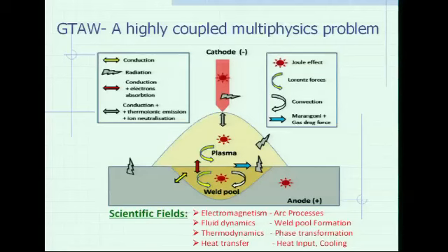And in this weld pool, you have many forces. The first one is the Joule effect, so heating. You have some Lorentz force due to the electromagnetism problem and the field induced by the electric current inside. You have also some convection, called buoyancy force. That means when you heat a fluid, the material is going up, and you have some motion of the fluid due to these things. Basically, I will go into it a bit later.